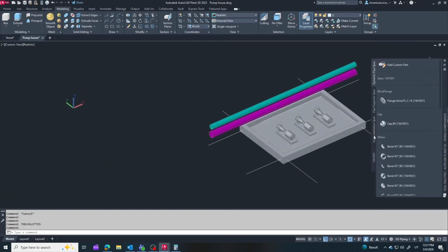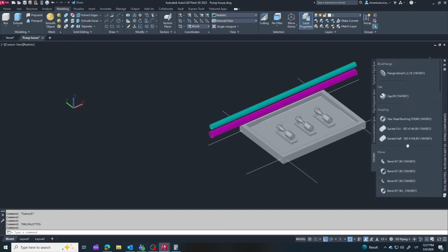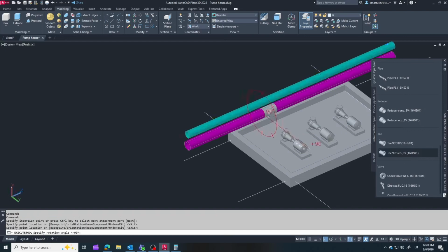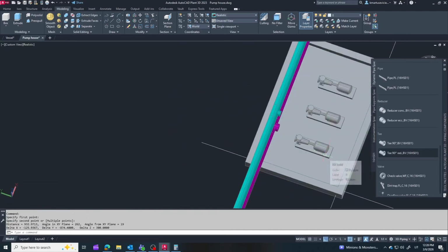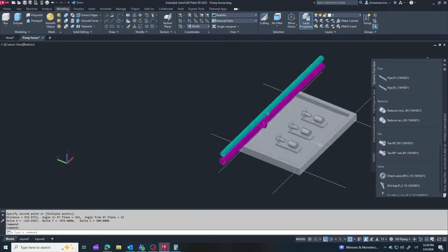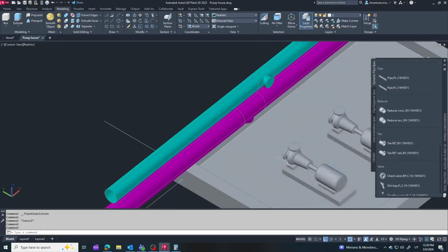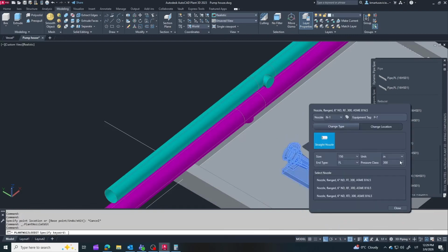If we keep the manifolds the same size as the pump nozzles, the fluid velocity inside the manifold will increase when multiple pumps operate at the same time. Higher velocity leads to higher hydraulic resistance and additional pressure losses in the system. Recommended fluid velocities for pipelines can easily be found in engineering guidelines and on the internet. For example, in water pumping systems, the typical recommended velocity in pump piping is usually around 1.5 to 3 meters per second.